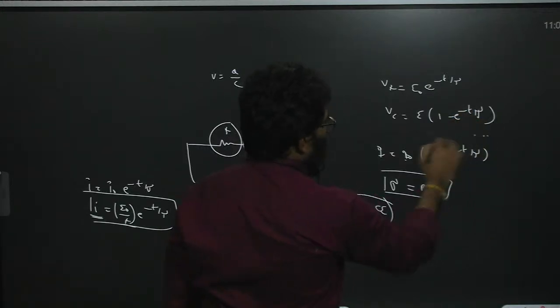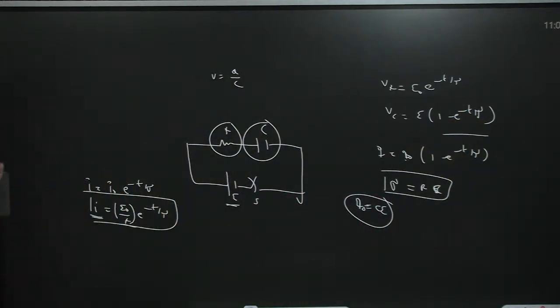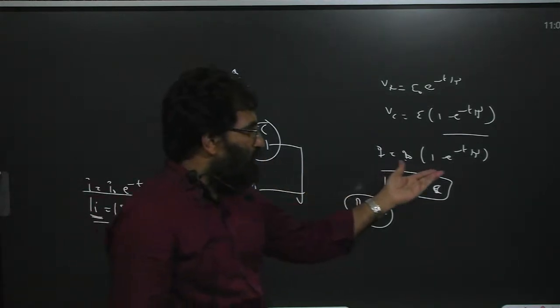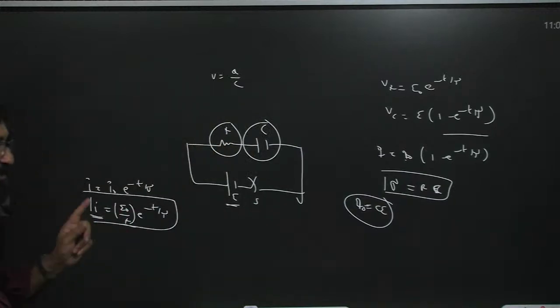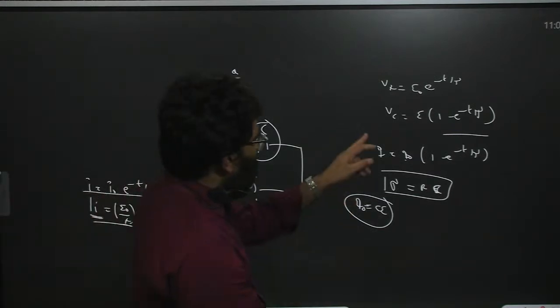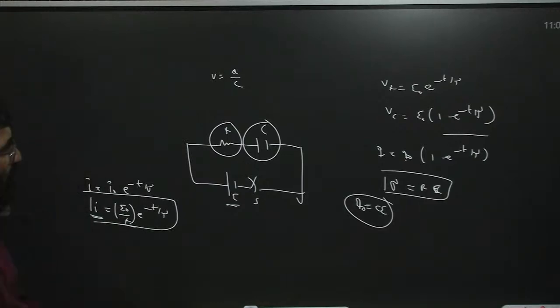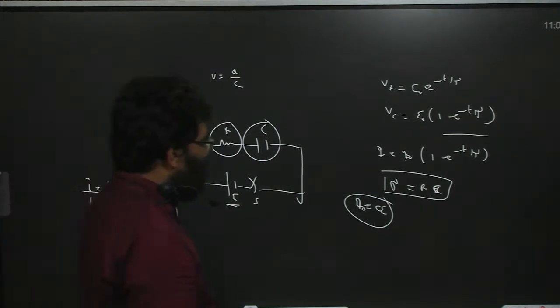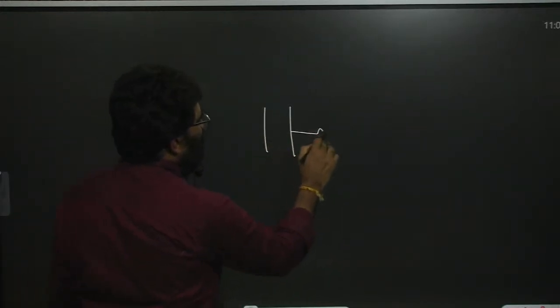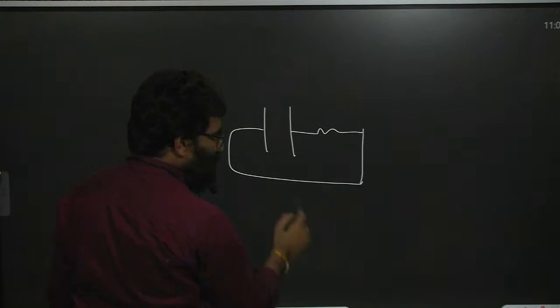This is a very important moment. So potential drop, current and the charges inside the circuit, we are getting like this. So charge is Q naught into e power minus t by tau. Tau is equal to R net into C net. So Vc, the potential drop across capacitance, is changing from 0 to E naught into 1 minus e power minus t by tau. So in the circuit, we are getting current like this. Now the capacitor is discharging. If the capacitor is discharging through one resistor, in discharging mode there is no voltage source.